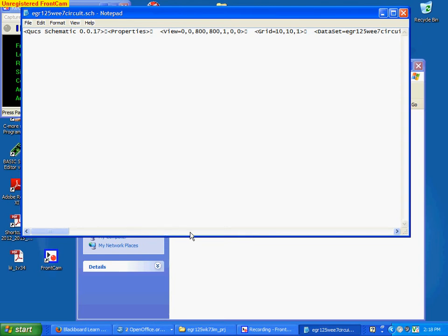It's probably between 2 nodes. I don't know what these numbers mean. It's not the net list that I'm used to. But what I want to do is I want to change its value. Remember the space bar, so I'm going to click between the 1 and the K, do a backspace, 0.5. So basically I just changed that to a half K ohm resistor.